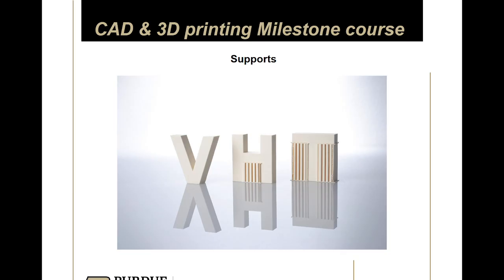So I printed it nose down, and I just used supports to support the wings all the way up, so they had a good surface finish. This is definitely kind of wasteful because it's a lot of support, but print orientation can definitely impact how your print comes out. Definitely keep print orientation in mind.